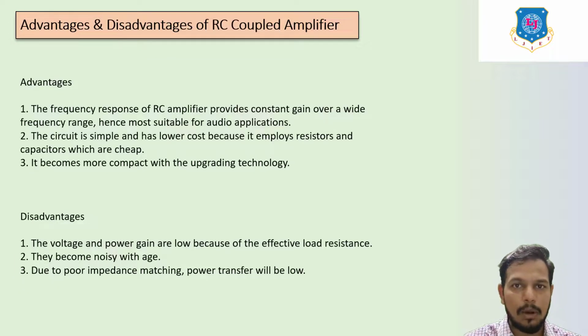Now let us discuss the advantages and disadvantages of the RC coupling amplifier. First, advantages. The frequency response of the RC coupling amplifier provides constant gain over a wide frequency range, hence it is most suitable for audio applications. Now, why is it providing a wide frequency range?